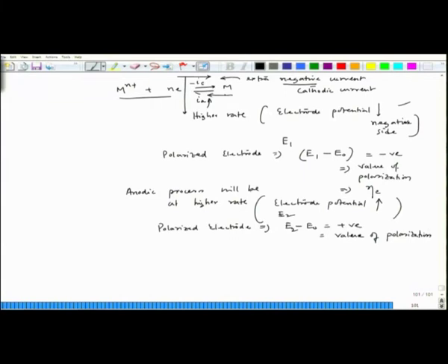And when the potential increases from the reduction potential at that equilibrium condition, we call it anodic polarization, and it is termed as eta A. And when we have this situation, we call it cathodic polarization, and the potential drops from the equilibrium value.